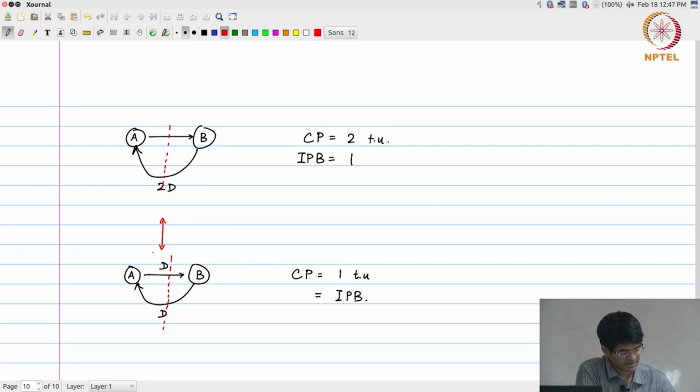right. So, in other words, for this direction I do plus 1, in this direction I do minus 1, and that is what has happened, right. The A to B edge which had 0 registers on it, I did plus 1 and it ended up with 1 register. The B to A edge which was going backwards had 2 registers on it, I do minus 1 and it becomes 1 register on it, okay.